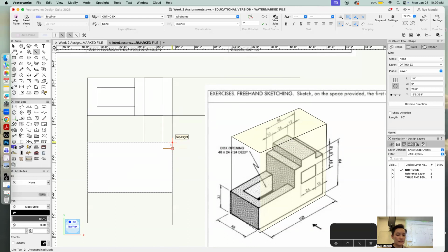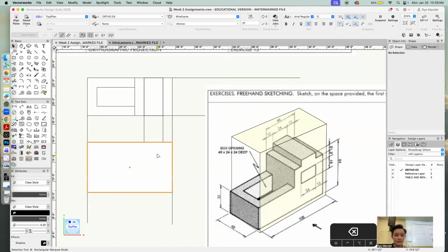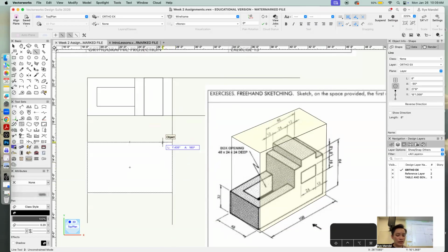So this is how you can easily do it in the snapping way. An alternative way to do it is, let's say these lines weren't here. I can still look over here and create a little extra line for myself that is, let's say, the 8 inches that is there. I can give myself my own snapping points that are already there. So that'll be 8 inches. This one's 12 inches. And I can just give myself those snapping points there.